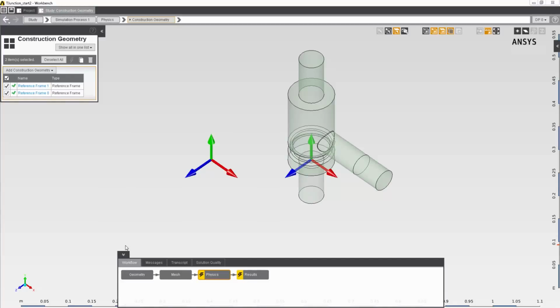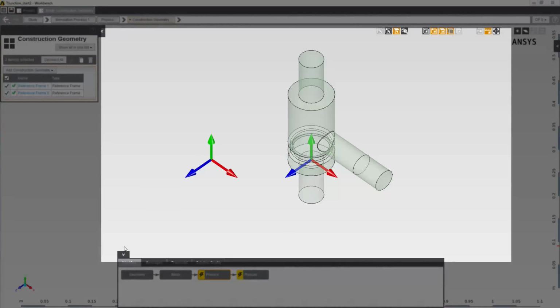Coordinates, vectors, velocities, and all other spatial quantities in AIM are interpreted relative to a specific frame of reference. By default, this is the global reference frame. For example, the position of a point on our inlet relative to the global frame is given by a vector with Cartesian vector components defined as the offset to this point in the x, y, and z direction of the global frame. If we introduce a new reference frame, the position vector relative to this frame will be different, but the point hasn't moved, only the frame relative to which we measure it.